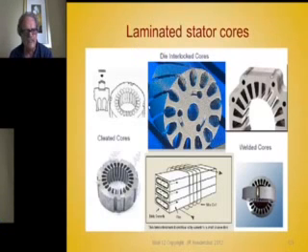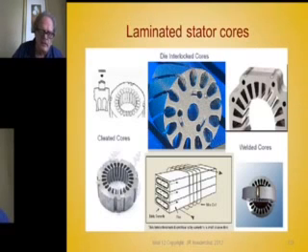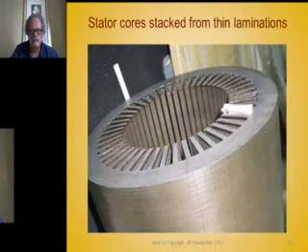Now, I think it's important to note here what a bad job this is. You see, that skew is not uniform. See all this jaggedness? Well, that cuts into the slot opening. If this is an induction motor, then you've reduced the cross-section of the die-cast aluminum material. That's a very bad job; that die needs maintenance. The servo system that does the rotating of that interlocking notch needs attention. It's a very poor job. I'm happy to have this picture to illustrate that to you.